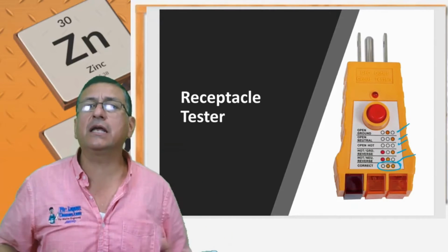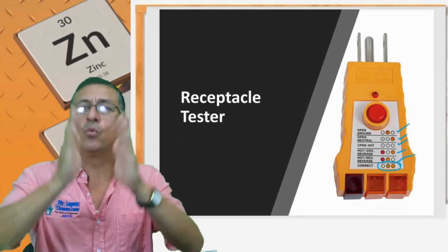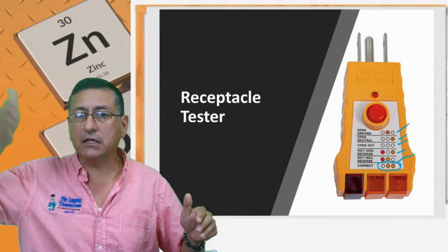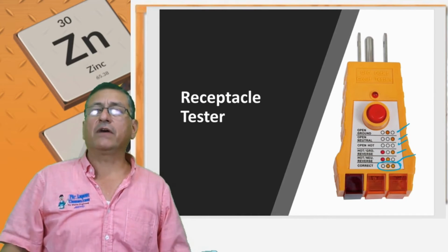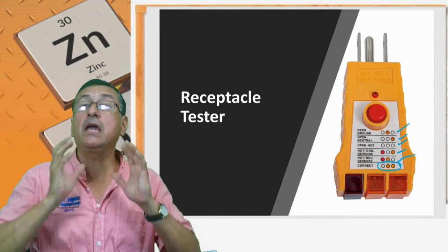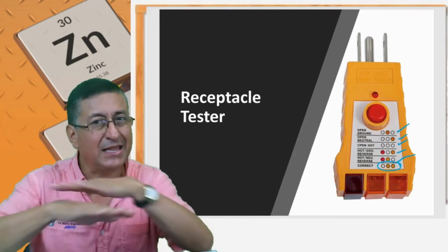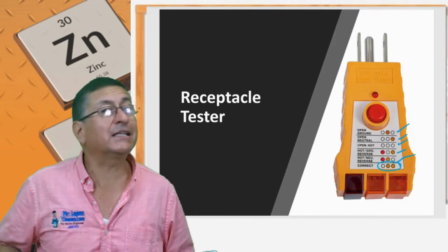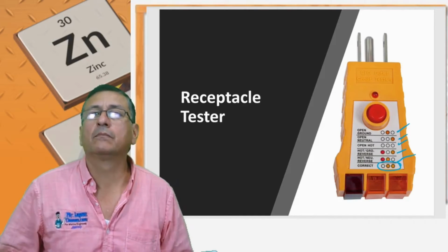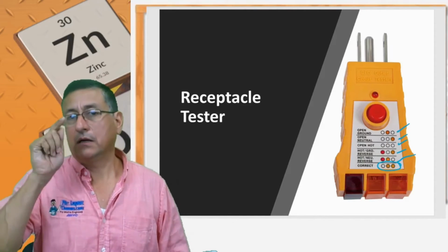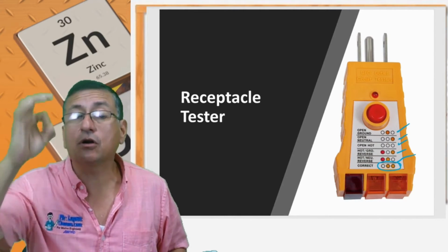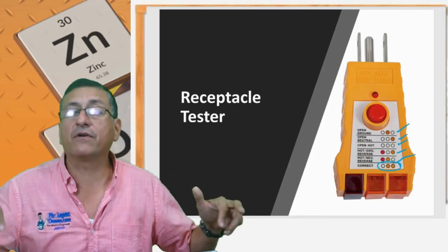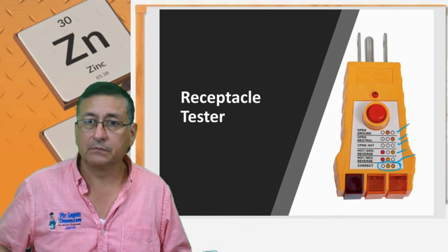Okay, but right now it's clear that I need to protect my boat with the galvanic isolator properly installed in the ground line. I cut the ground and I insert the galvanic isolator. The other one is keep my boat clean, dry, no water, no humidity. The other one is verify that I don't have reverse polarity. I check with the indicator on the panel, and also with the tester I check in the outlet that I don't have reverse polarity in any outlet.